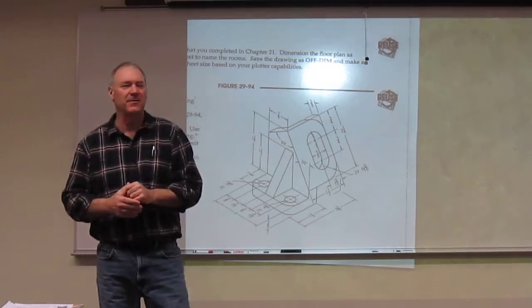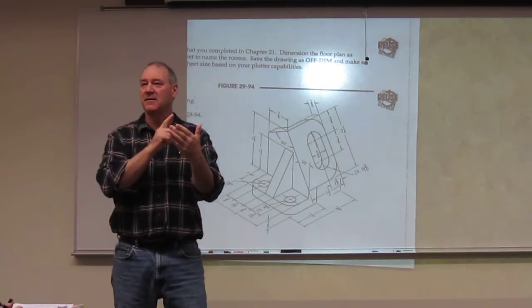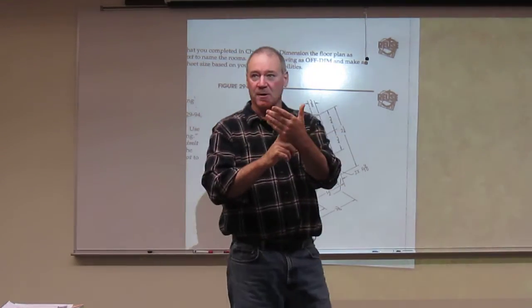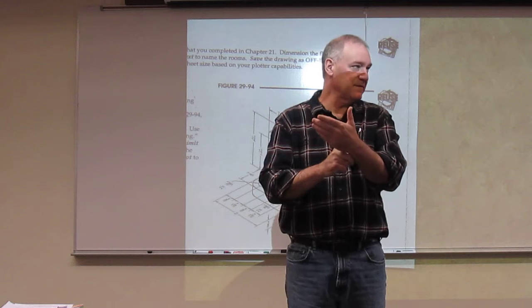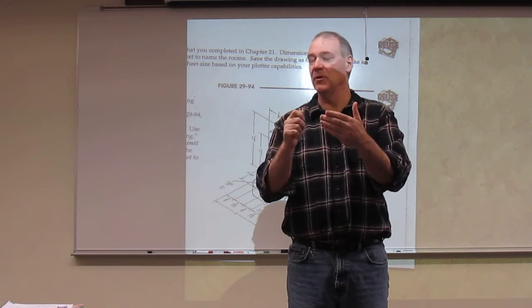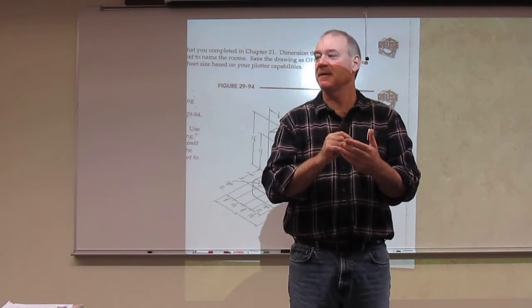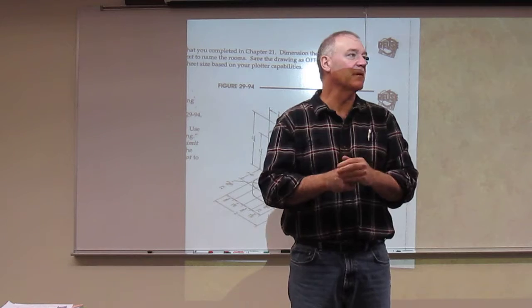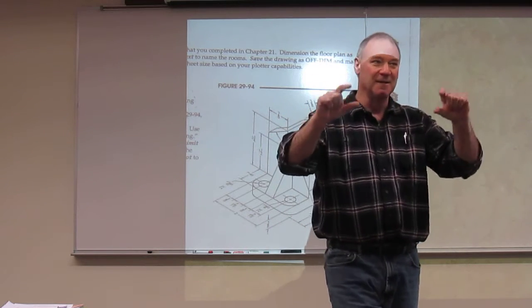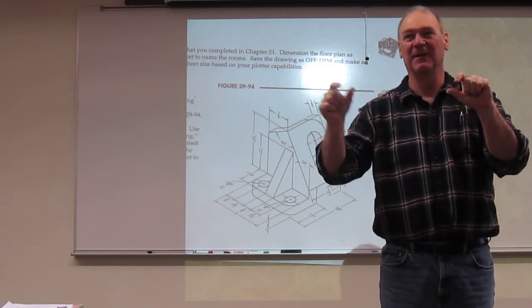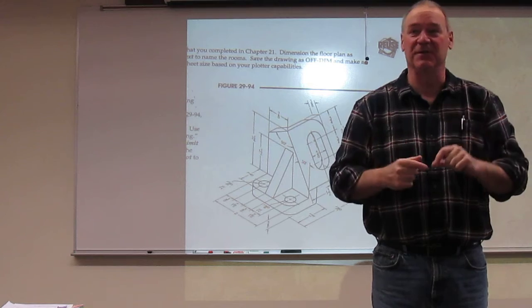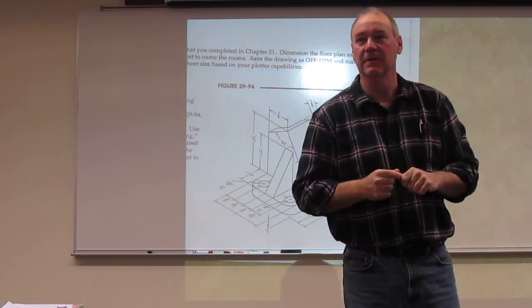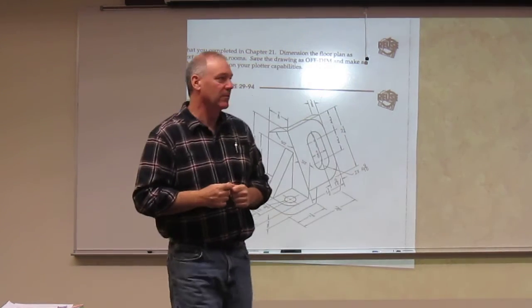Remember, typically we would say all dimensions plus or minus 0.000 or tolerancing to 3 places. And then you would always put UOS if you did anything different on the drawing. Because you're giving them a note saying, hey, go this, but I put UOS on there. There's something else out there that switches. Be aware of it. Okay. That's what that UOS is meant for.